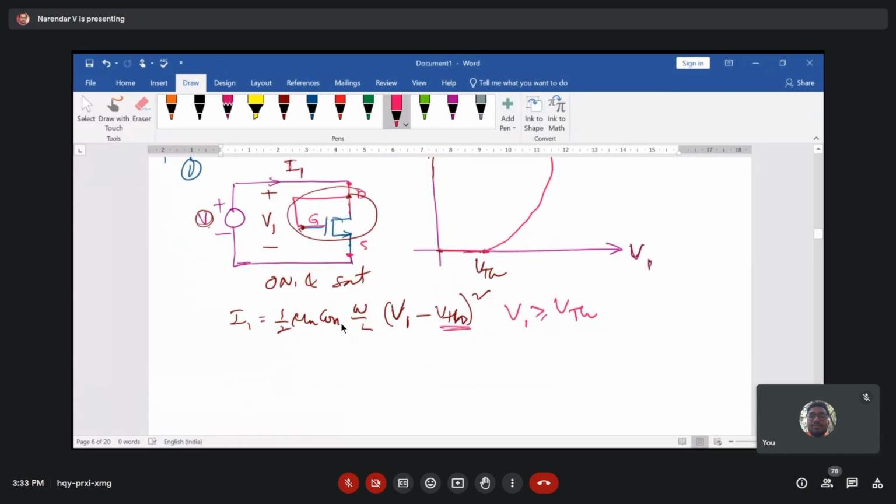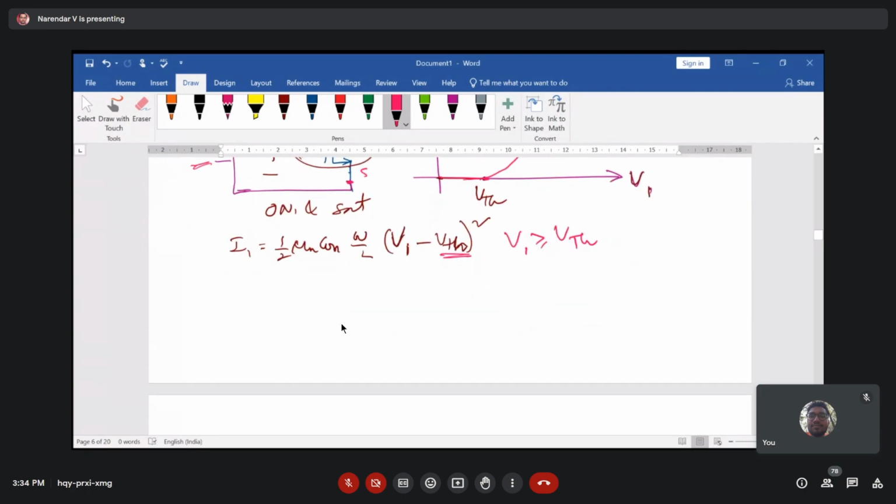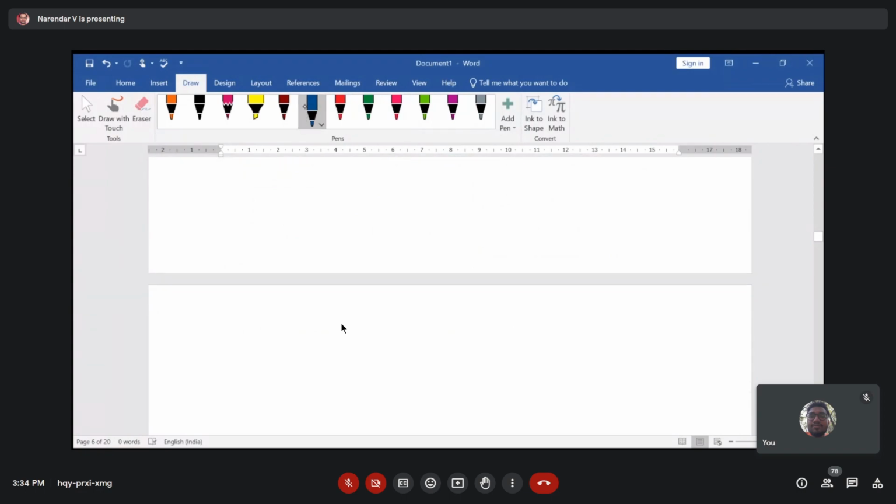Now we are applying a voltage here. Instead of voltage, what we are trying to do is make the biasing here, right? If we apply a current, then we can take the voltage also. So how do we make that configuration? Let's try the diode connected MOS transistor again, this one, a two terminal device. Now we apply a current source here. We consider that this is a diode, and across the diode we apply a current called I1, and because of the current there is a variation in the voltage across this MOS transistor.